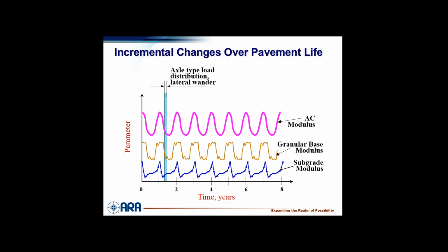And then at every point in time, you have traffic loading. You have 4 different types of axles, single, tandem, trident, quads. You have a huge axle load distribution, and you have lateral wander going on. As the trucks wander down that lane, sometimes you're here, sometimes you're here, and all that affects performance. That affects rutting, and that affects fatigue cracking dramatically, both of them. And then you have traffic going up every year, annual increases. You have concrete modulus keeps changing. Even the asphalt has aging in it. There is a component of that in here, but it's not very good. The top inch or something.